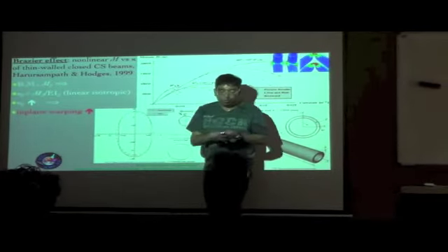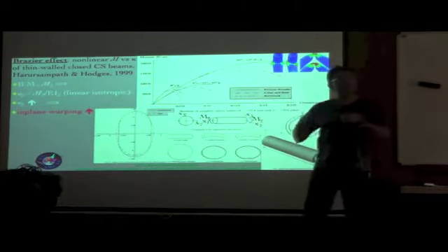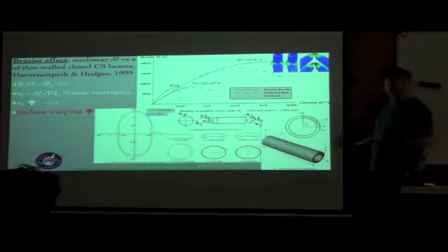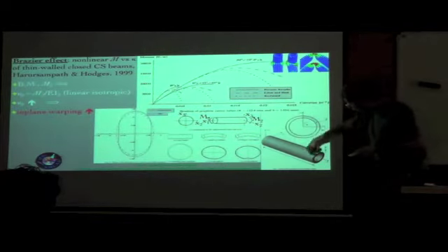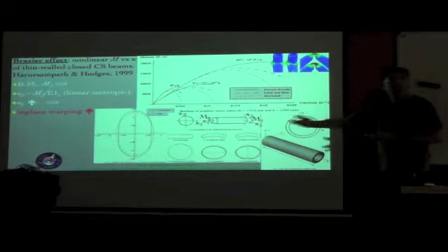So you basically see that, and this is an example of in-plane warping. Again, we've been talking about warping, remember, as a 3-dimensional field. So in other words, it has 3 components, W1, W2, W3, along the x1, x2 and x3 directions respectively. What is along the x1 direction, which is along the beam reference line, is what we call the out-of-plane warping, because the plane section no longer remains plane, it basically warps.